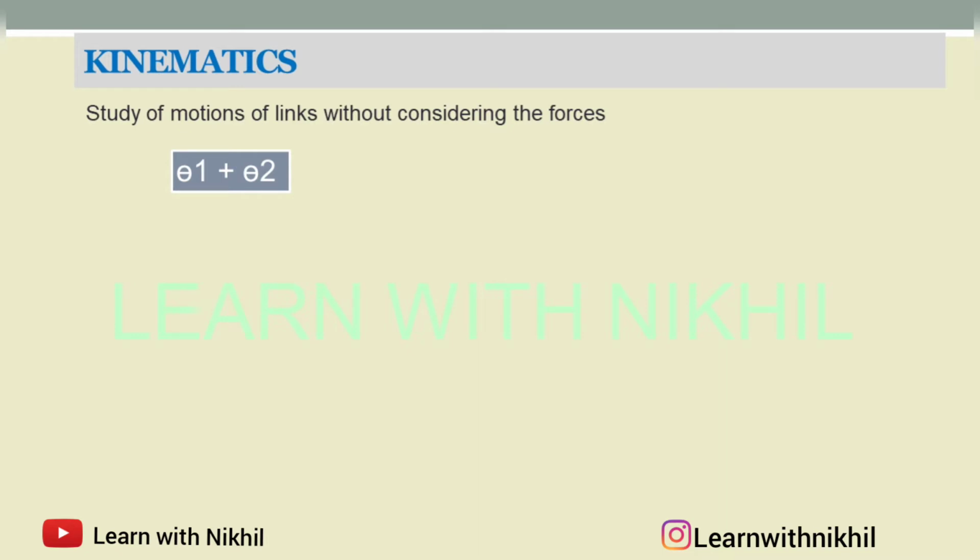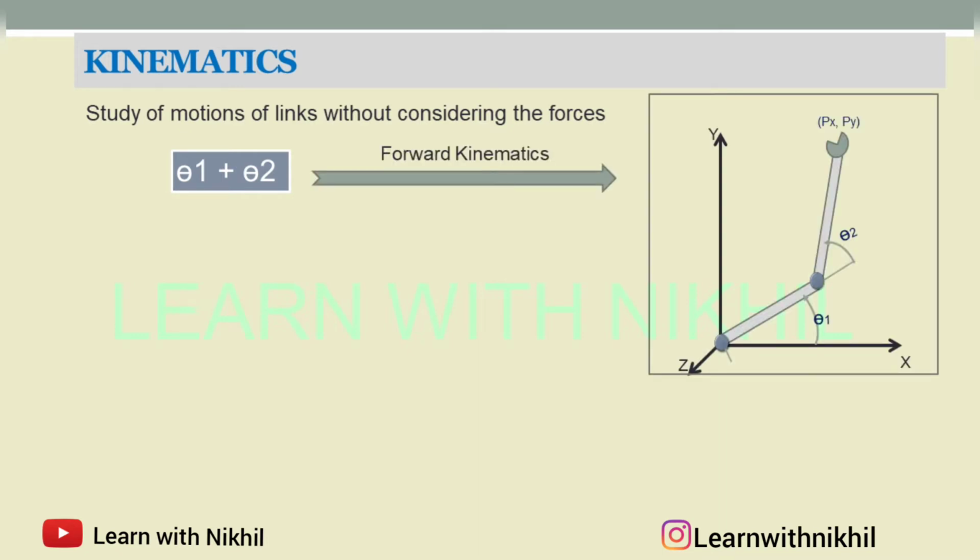Now to understand kinematics, in forward kinematics we have the values of theta 1 and theta 2. So we have the angles. When we know the angles, we find out the coordinates. So this is the robot, and when we know the values of the angles, theta 1 and theta 2, using these angles we find the coordinates. So this is the position of the end effector. We find this using this. That is the forward kinematics.